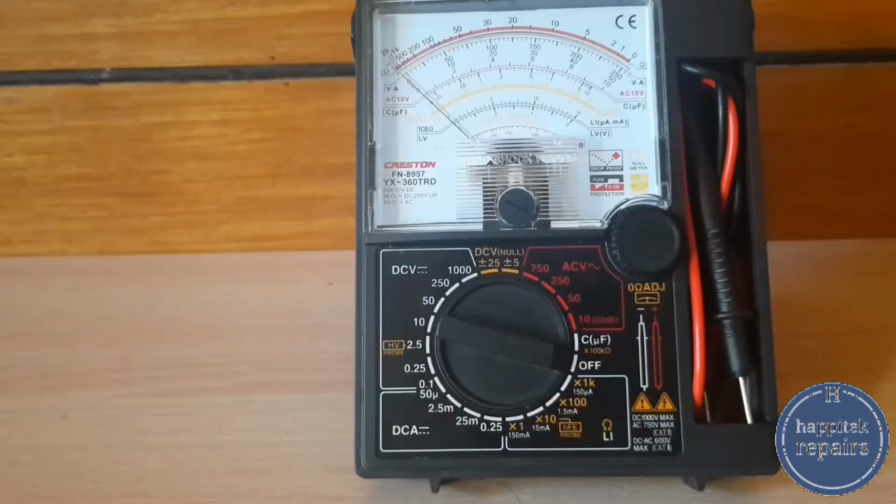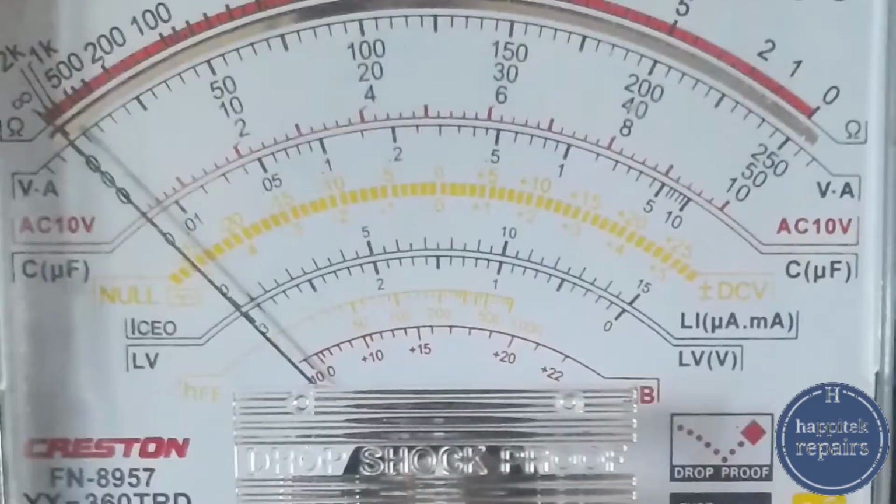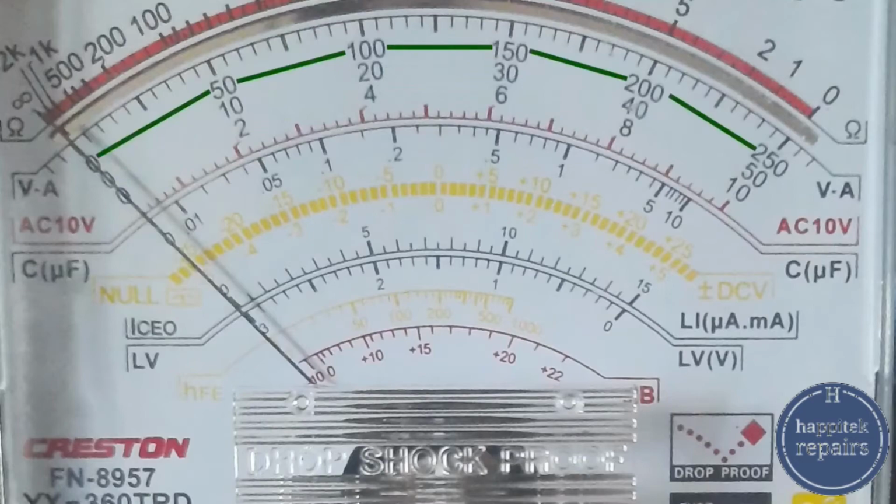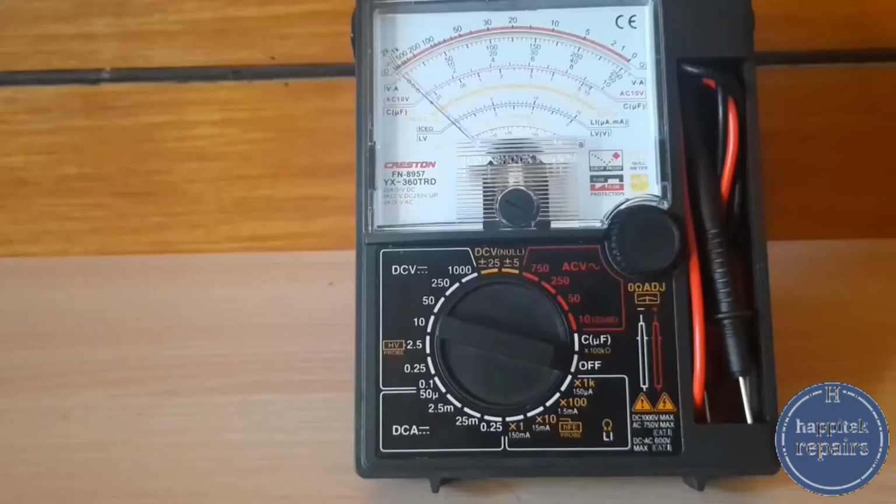It is necessary to understand the difference between the AC meter setting and the AC meter range. There are 3 meter range scales: 0 to 10, 0 to 50, and 0 to 250. When using the voltmeter scale, it must be according to the setting we use in measurement.